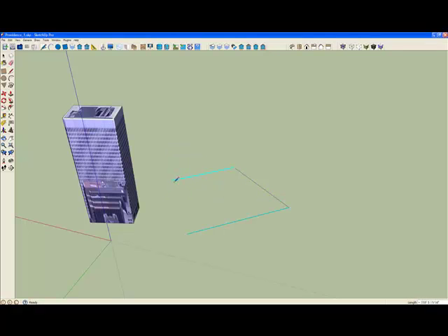There's also inferencing on arcs. So now we've created this edge parallel to the first edge, and then we'll see that it's also at its vertex. Now we'll go and create an arc, and it'll tell us that that arc is tangent to both of the edges, and it can be tangent on either side.